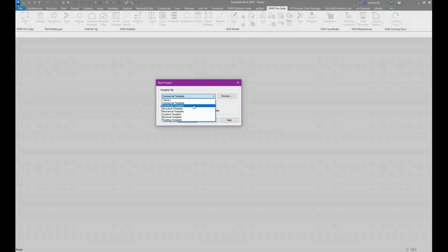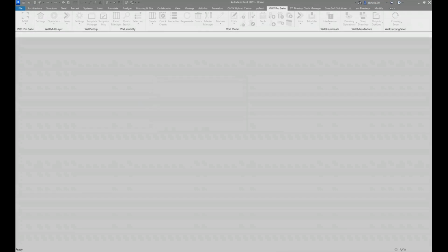The only reason is because they already have the preset wall thicknesses or structural layer thicknesses, because for wood, say if it's a 2x4, you'll have a 3.5-inch thickness for your structural layer. For steel, if it's 4 inches, it's 4 inches. That's it. So they already have a few walls pre-created for you. So if you're in wood, residential, steel, commercial, doesn't matter even if you're doing commercial projects with wood. It's just that it has the wall types that you need. Okay, so let's go inside the commercial template here and let's go.